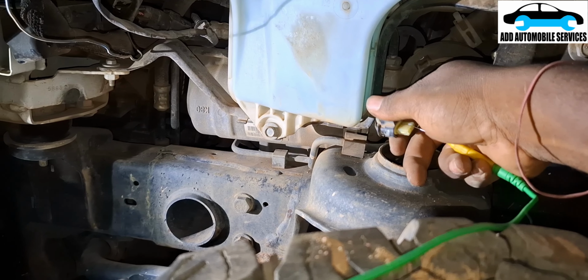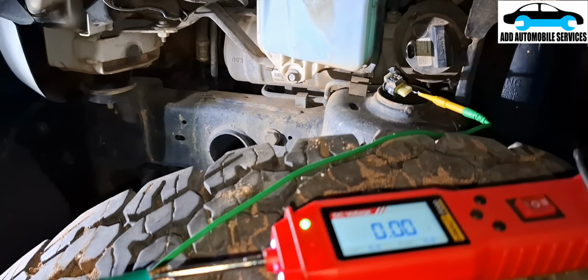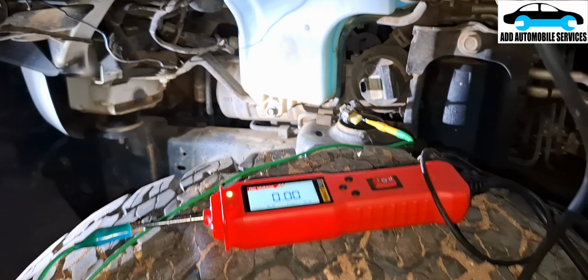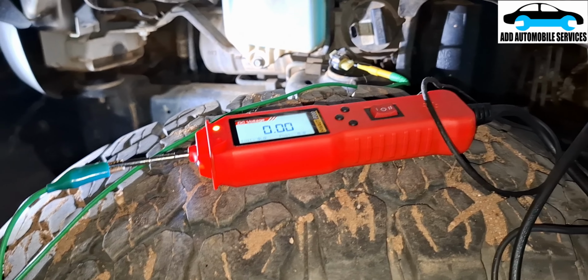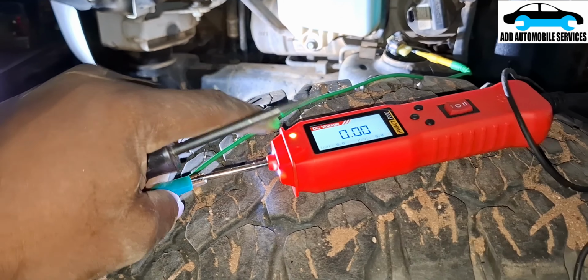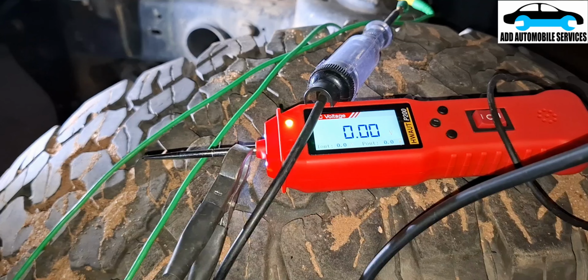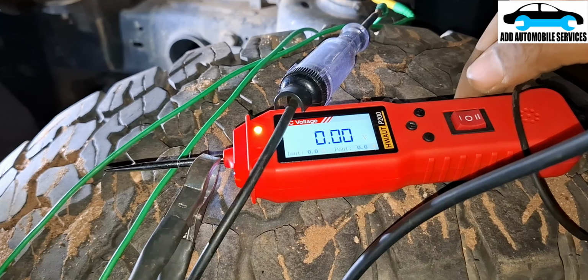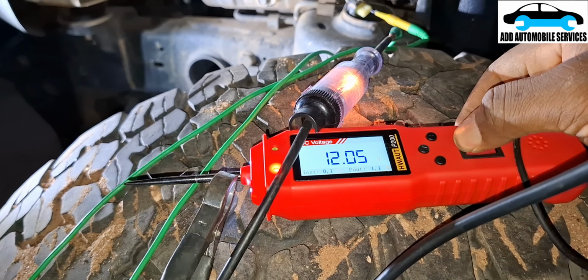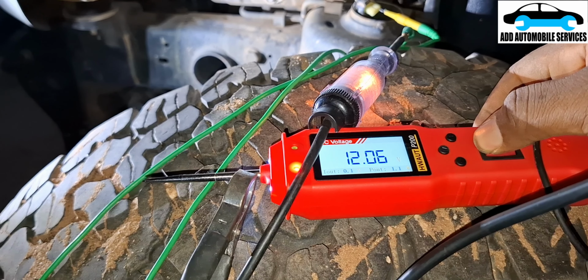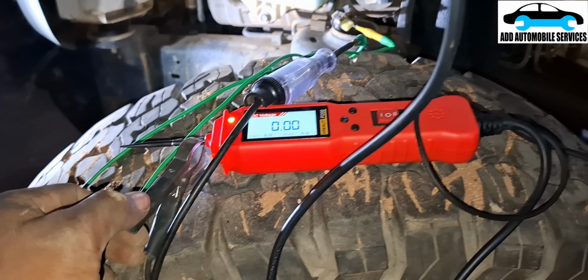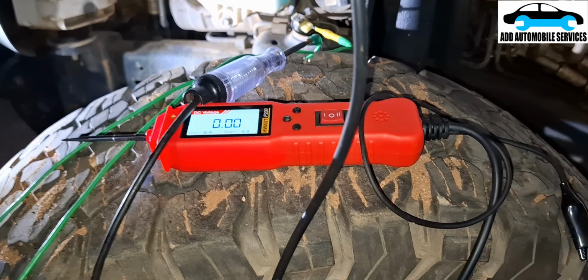and check it. So you can see it has turned on ground, which tells me that my ground is okay. If I want, I can test this ground by connecting this side to my test lead to my small power circuit tester. So when I send power, you can see my test light is on. When I release it, you can see it goes to ground. So that tells me that my power and ground is okay.